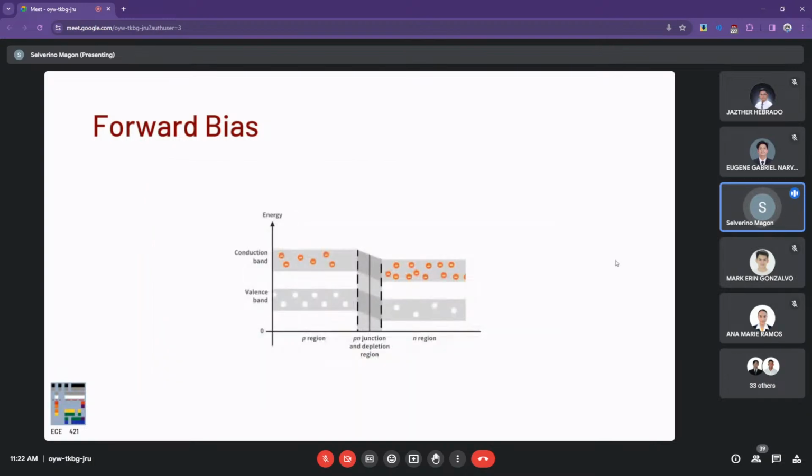From the point of view of an energy diagram, forward biasing a diode increases the electron density in the conduction band of its n region. We will see that the energy levels of the valence and conduction bands in the n region are elevated, allowing free electrons to cross the junction. A key to understanding this is that electrons want to move down and holes want to move up. So, by pushing the n region up more, the electrons can drop into the valence band, or if they have sufficient energy, can move directly into the conduction band of the p-type material. Also note that the depletion region is narrower at the forward-biased equilibrium.